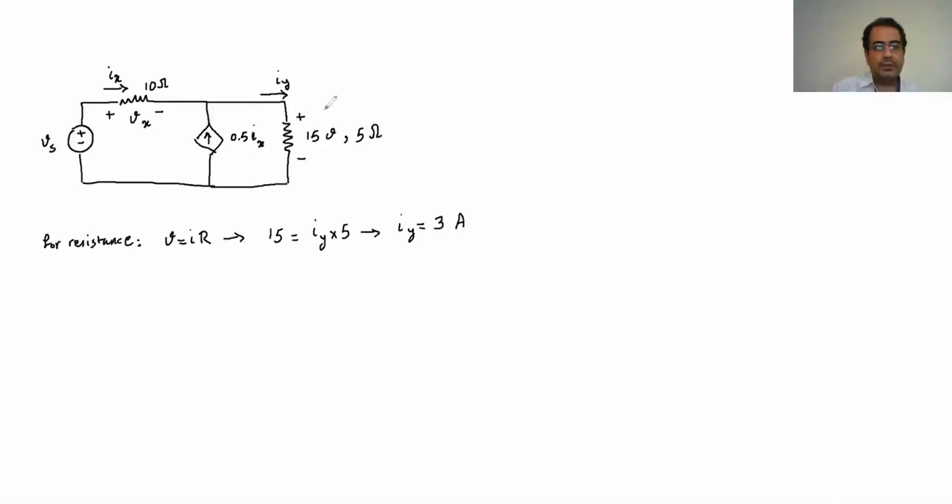Now, the next step is that I have to go here. The other unknowns are these three: either I have to calculate Vs, Ix, or Vx. I have to find one of these three. The Vs I probably cannot find right now. The Vx, I can't find. But the Ix, I might. So if I look at these top nodes here, I call it, for example, node 1.